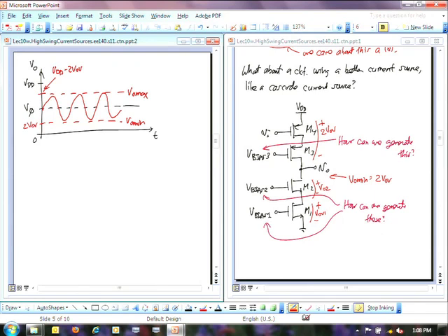So with a cascode, one of the nice things about these cascode type devices is they give you a lot of gain. But one thing you sacrifice is you're going to lose some swing. And what's more important, gain or dynamic range? Sometimes gain is more important. Sometimes dynamic range is, especially in communications, dynamic range is more important. Okay, but let's stick with this cascode here.